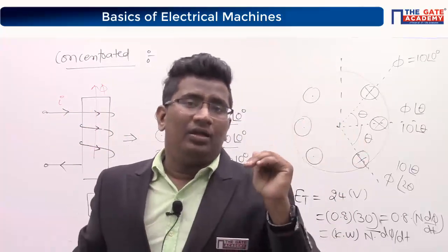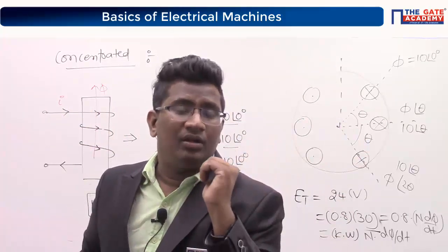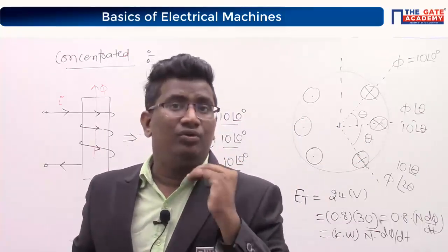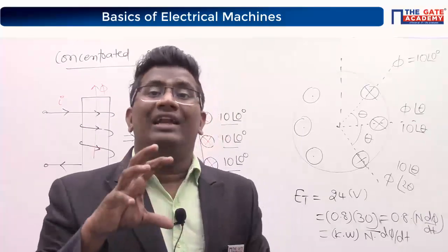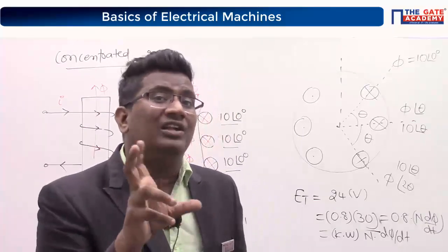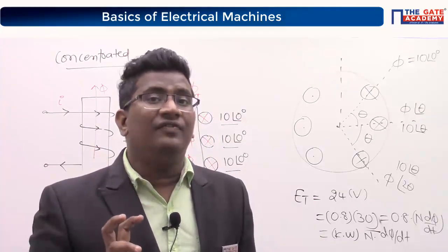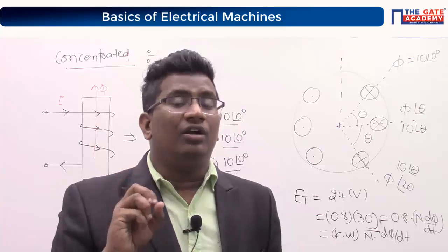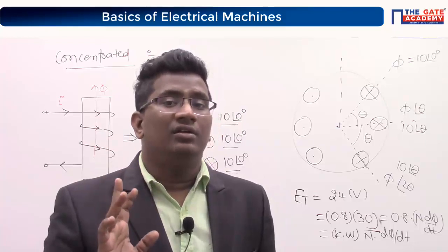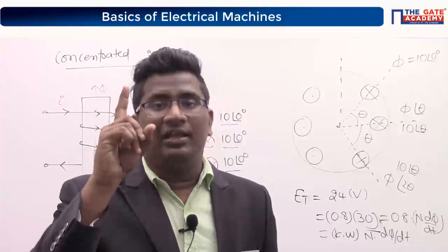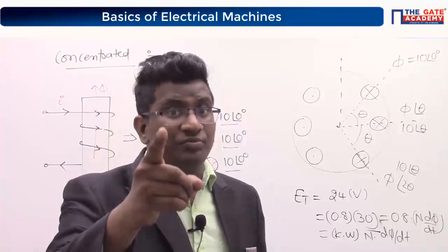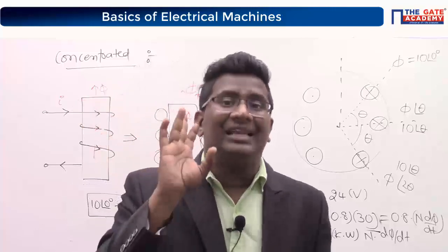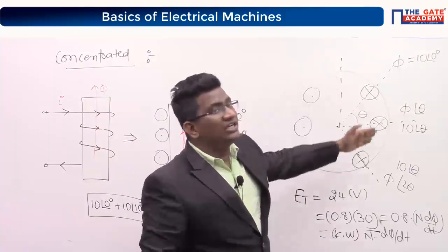I hope you know about rotating magnetic field. Have you heard about it? That we will see in induction motor. But right now I am asking, do you know rotating magnetic field? Will it produce for distributed winding or concentrated winding? Distributed only. Soon I will prove distributed winding will produce only RMF. Concentrated gives 0, no RMF. That is the reason why we are using distributed winding.